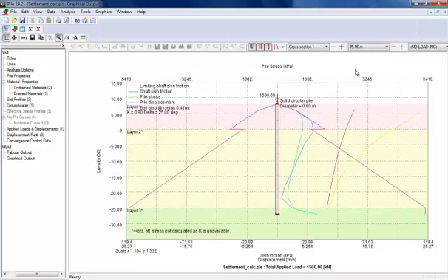But as well as just looking at two different cross sections of piles, so instead of, for example, just comparing 600 mil and 700 mil, the settlement calculation goes further than that, and you can actually look at the difference it makes by reducing the length of your pile. And as you can see, the value is actually appropriately changing. So it really helps you understand how your pile is behaving according to settlement, and it's very helpful that way.